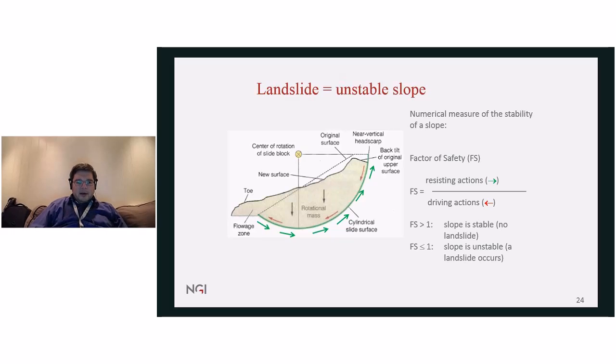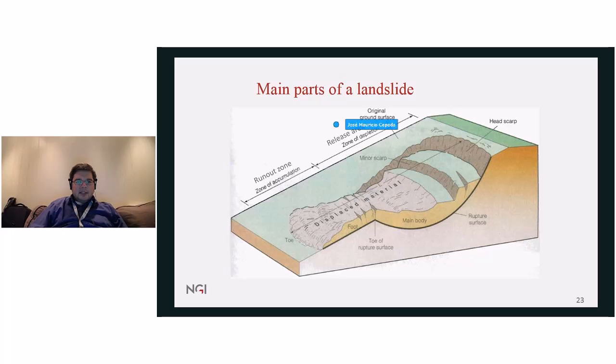So when we think of landslides, we have to ask ourselves which phase or part of a landslide we're analyzing, if we're analyzing this part or if we're analyzing this part, and also think about our mitigation measures. Where are they focused? Are they focused to avoid initiation here, or are they focused to protect exposed elements in the runout zone? Because then the type of measures are going to be different.